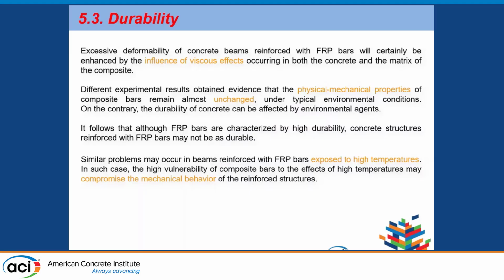And finally, of course, there is the key issue regarding the behavior of FRP rebar when exposed to elevated temperature. That can be mainly associated with the organic nature of the resin which composes the FRP bar. In fact, they present a glass transition temperature which usually varies between 60 and 100 degrees. So even for relatively low temperature, their mechanical behavior can be affected, and so the whole mechanical behavior of the reinforced concrete element can undergo some changes, either in terms of failure mode or mechanical properties.